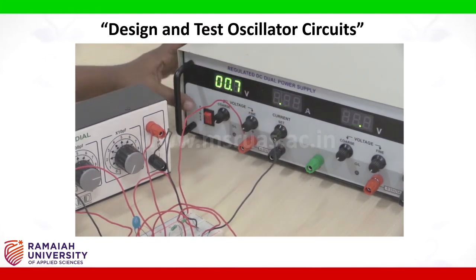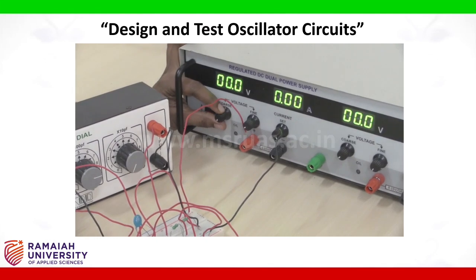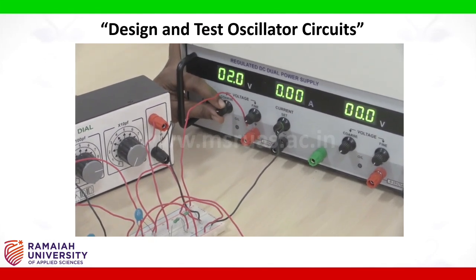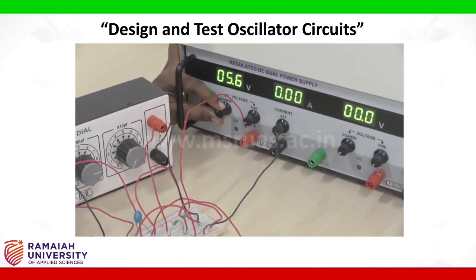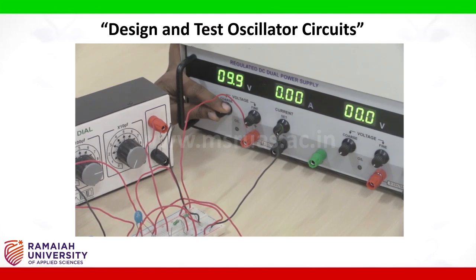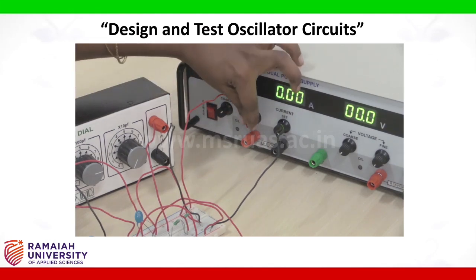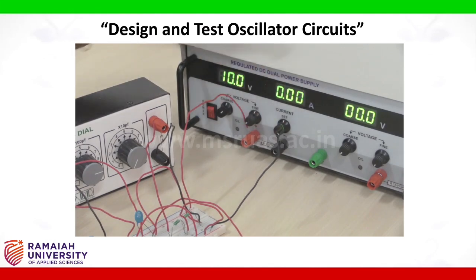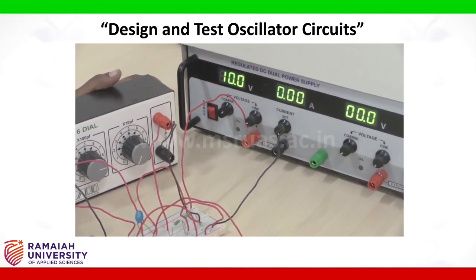Switch on the supply. Set 10 volts as the voltage reading. So 10 volts is the DC supply given to the circuit.